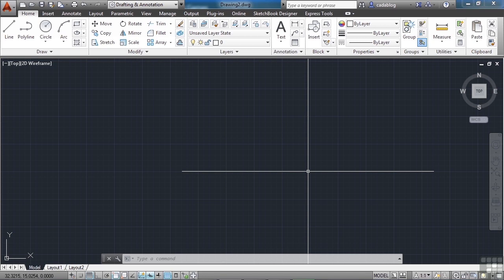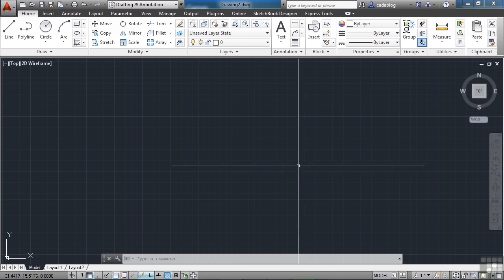The solid command and the donut command are two different unique commands and object types in AutoCAD. The solid command creates a 2D filled polygon. The first 2 points define one edge of the polygon. The third point is diagonally opposite of the second point, and the fourth point is diagonally opposite of the first point. That's confusing, and I agree with you completely.